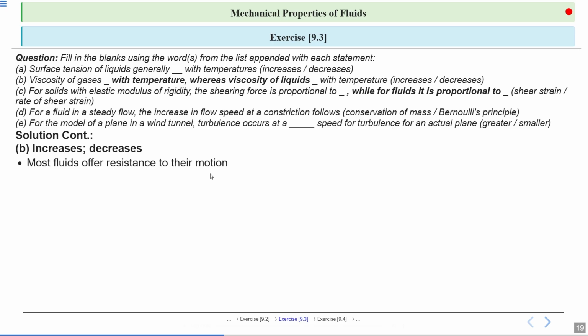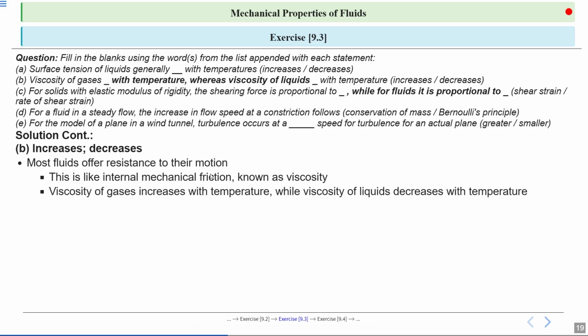Most fluids offer resistance to their motion. This is like internal mechanical friction known as viscosity. Viscosity of gases increases with temperature, while viscosity of liquids decreases with temperature.